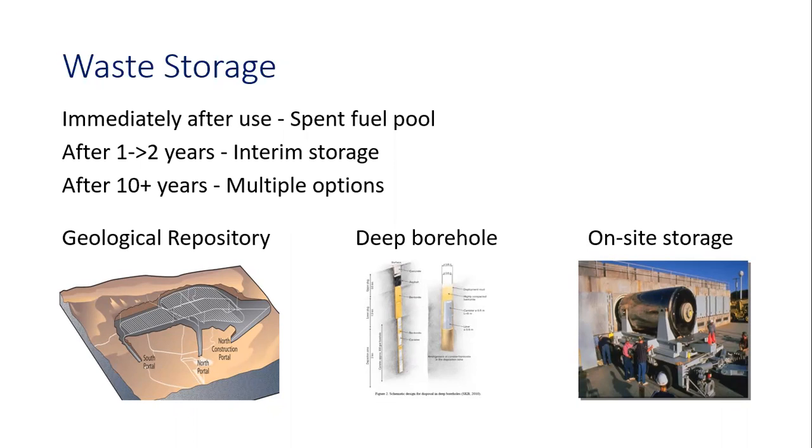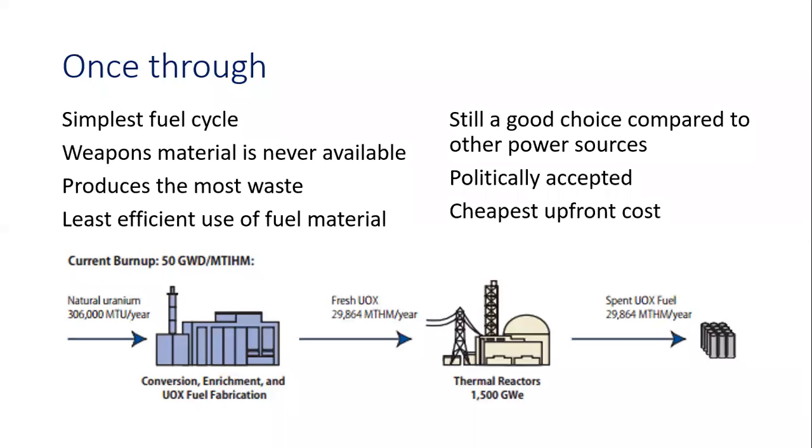There should be reasonable accessibility for the plant for receiving and dispatching heavy shielding and radioactive materials. Next one is the type of land. The substrate must be strong enough to support the heavy reactors, with bearing pressures of around 50 tons per area. These are some of the factors considered for the selection of a site.